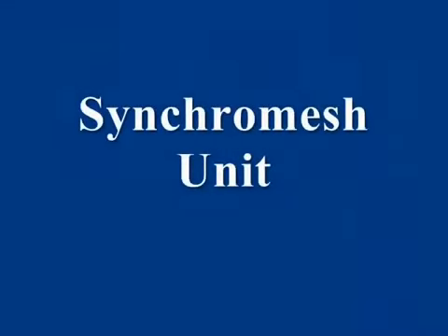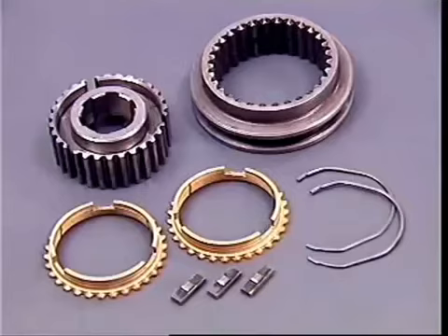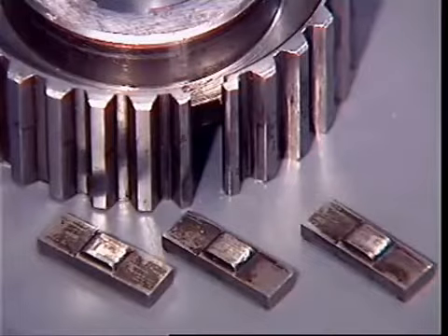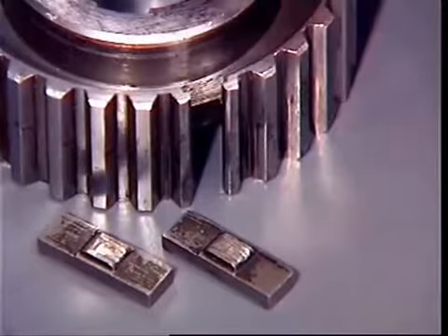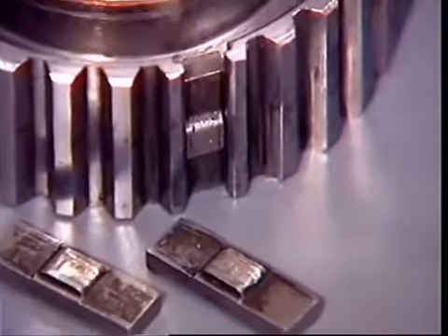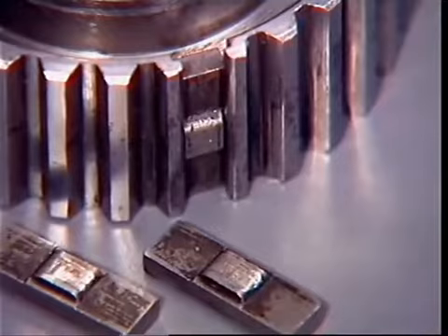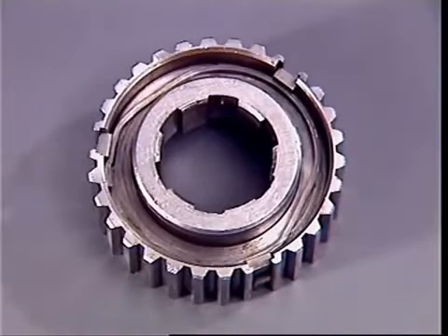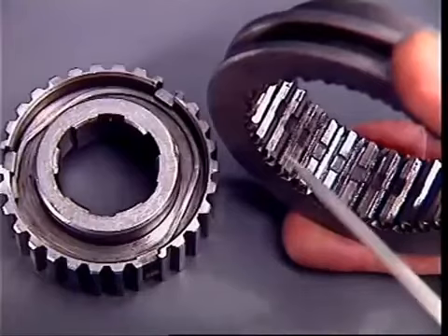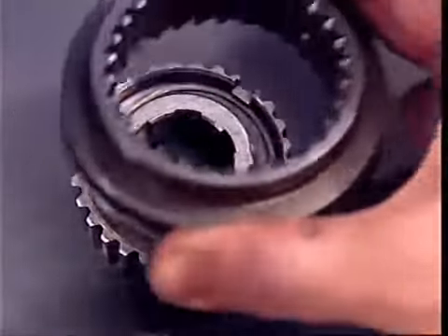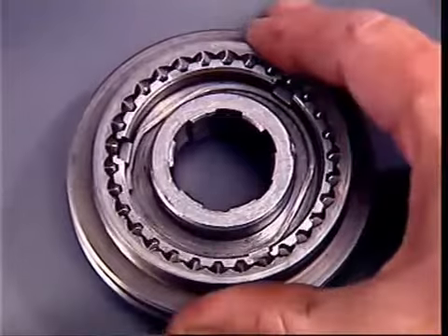A Borg-Warner ring type of synchromesh unit is commonly used to synchronize the speeds of 2 gears before engagement. 3 metal inserts with a ridge fit into slots in the hub. A radial spring at each end holds them out, so that the ridges locate in a groove inside the sleeve and hold it centrally on the hub.